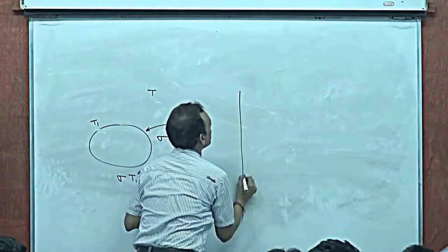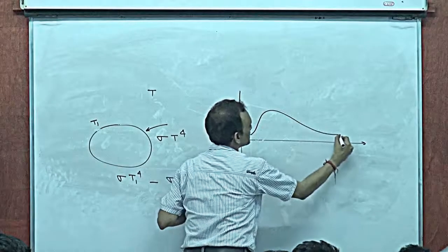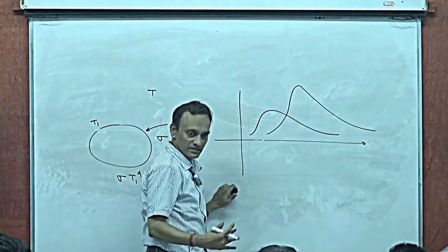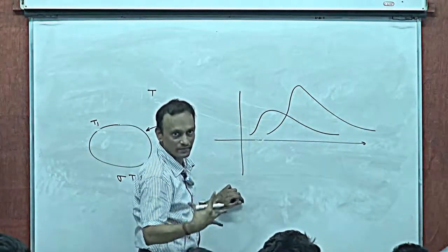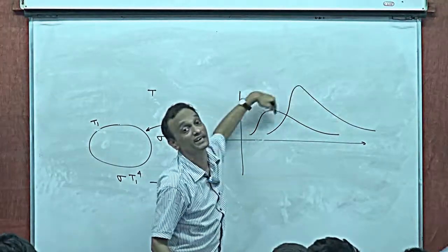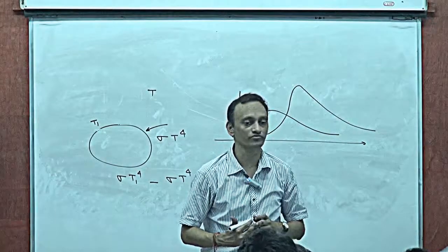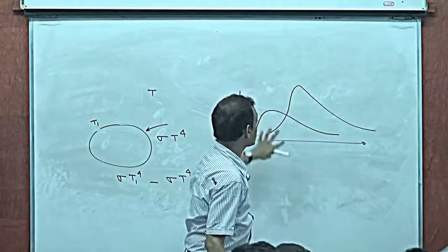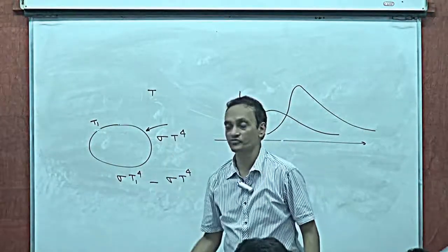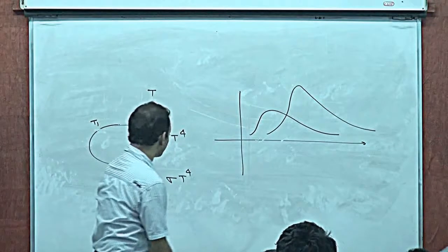So the radiant tubes that are modeled and created are based on this premise. Wet paper has this characteristic, and the hot radiant tube, which is at a high temperature, will have this characteristic to dry up the paper. So they will try to match these bell curves to the extent they can, so that there is optimum utilization of heat emitted by the radiator. This is the major problem of radiant heat transfer, where they have to match the emission and absorption characteristics of the entities involved. So this bell curve has to be taken care of.